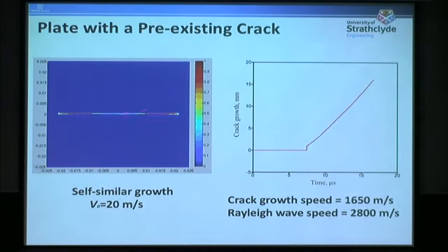What we are seeing is that the crack propagates similarly from left and right, and we can easily calculate the crack velocity as well. For this particular case, this velocity is lower than the Rayleigh wave speed, which is the upper limit that a crack can grow for this material. So our speed is less than this, so we are in good shape.